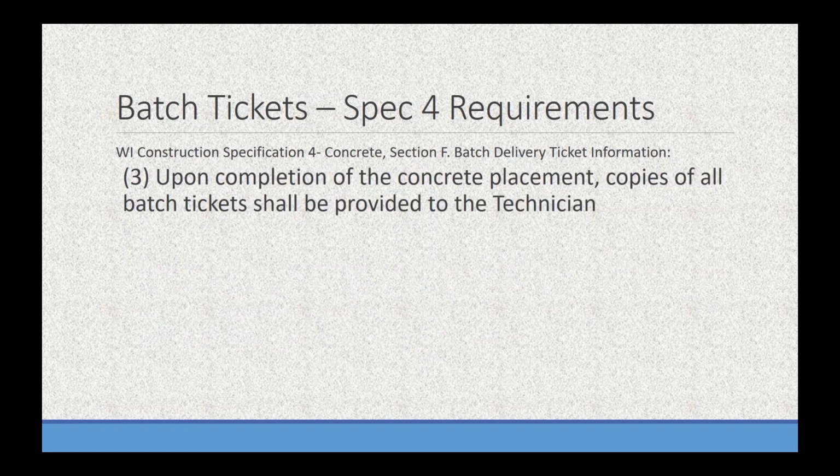Lastly, upon completion of the concrete placement, copies of all batch tickets shall be provided to the technician. So hopefully we'll have most, if not all, well before the completion of concrete placement, because like I said, if we're not getting them, looking at them and checking them until after it's poured, if we run into issues where the concrete doesn't meet, it's not going to be a good situation.